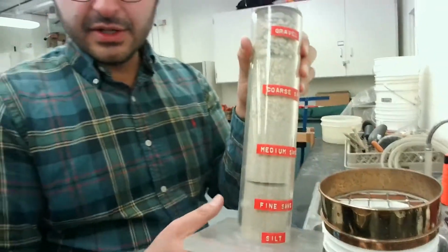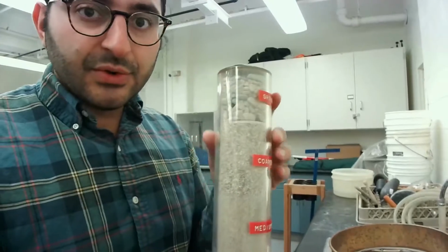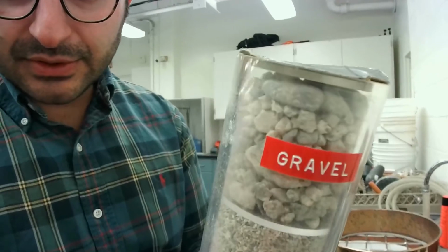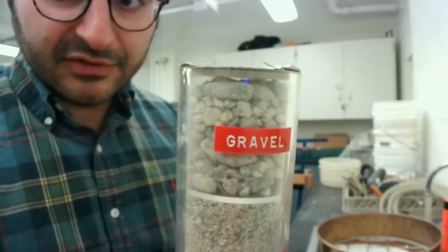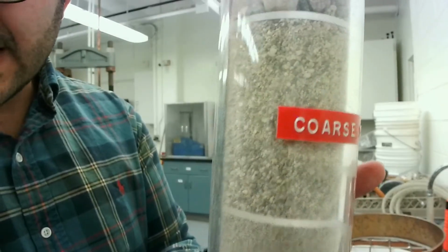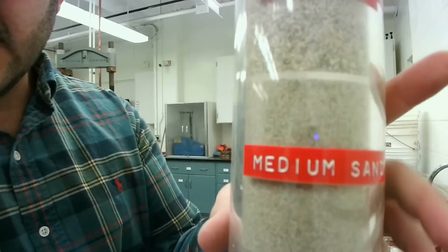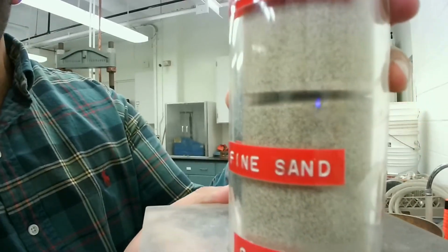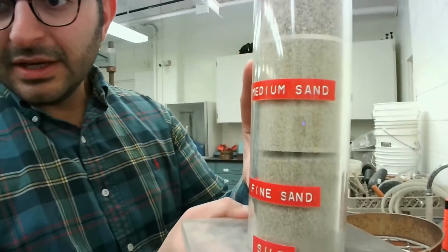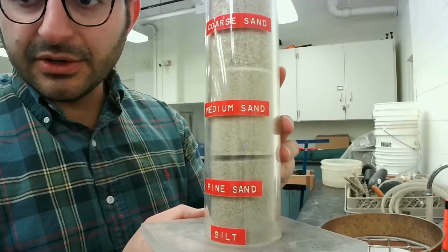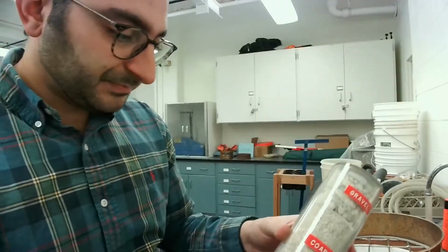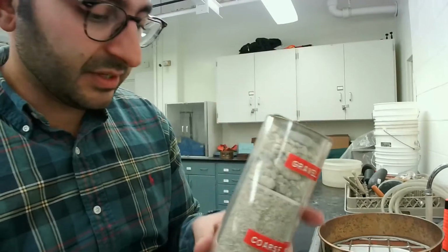This little thing here is one thing that could actually show you these main different solid particles. So you have gravel that's above 4.75 millimeters, and then you have these coarse sands, then you have medium sand, which is a little bit finer, and then you get into the fine sand, which is very, very fine. The bottom two are probably more what you would see when you go to the beach, right? So the medium sand and the fine sand is very close to beach sand, actually. Okay, and then you have the coarser stuff on top.